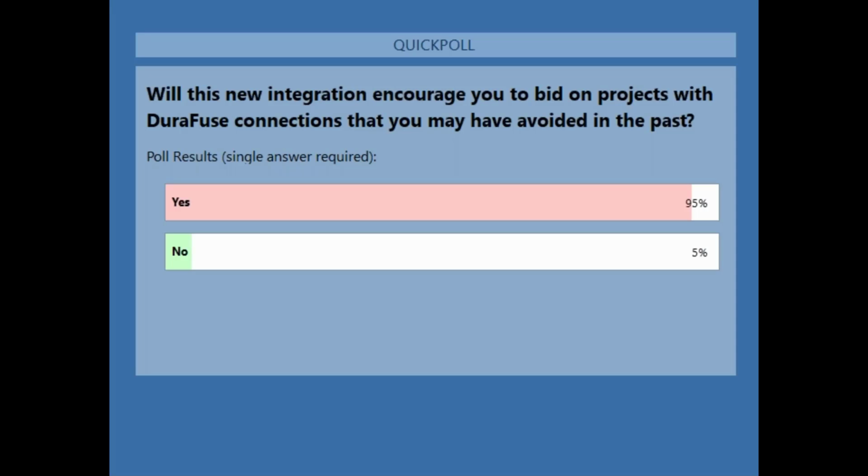Let's see, there's a question up here above: are there any connections to the web? Everything's going to the flanges of the columns. Yeah, that's a good question. So when you have beams that are framing in from the orthogonal direction into the columns, we have details that just have a shear tab that's attached to our cover plate at the connection.